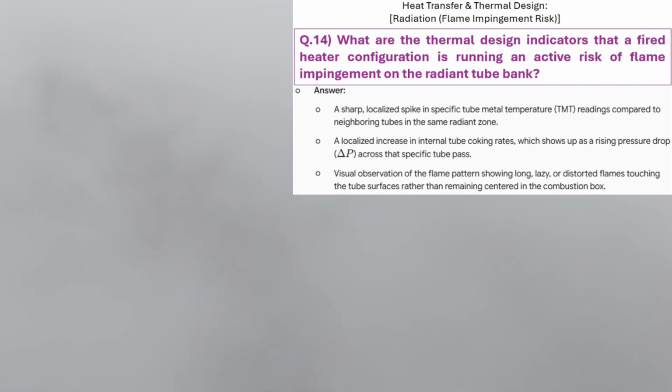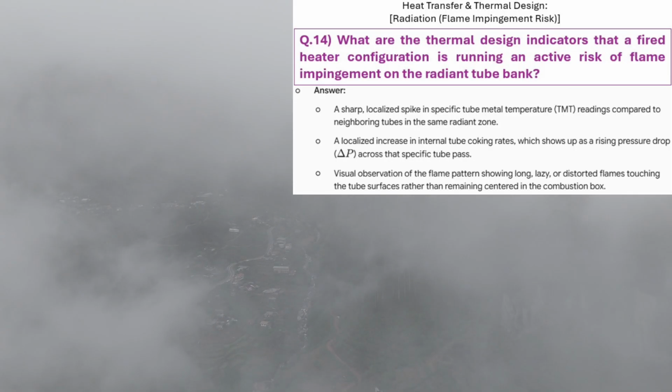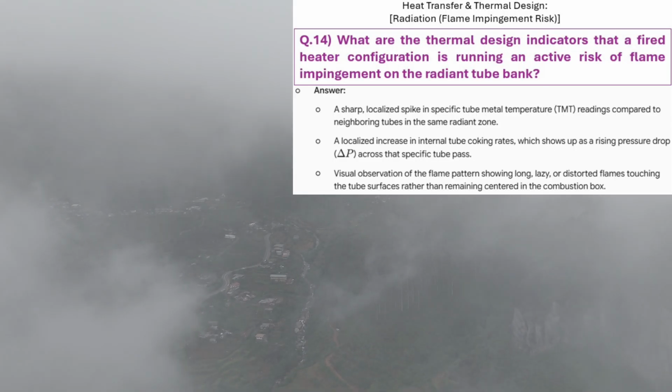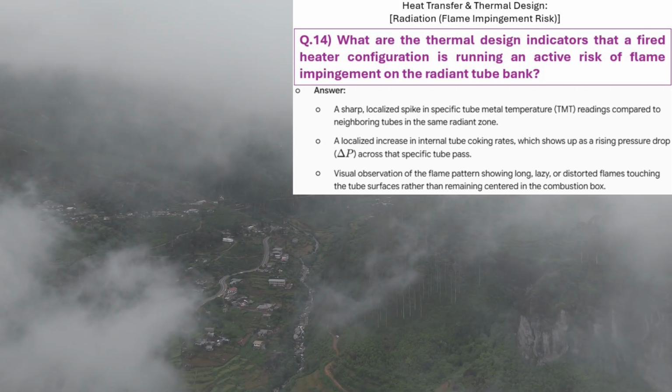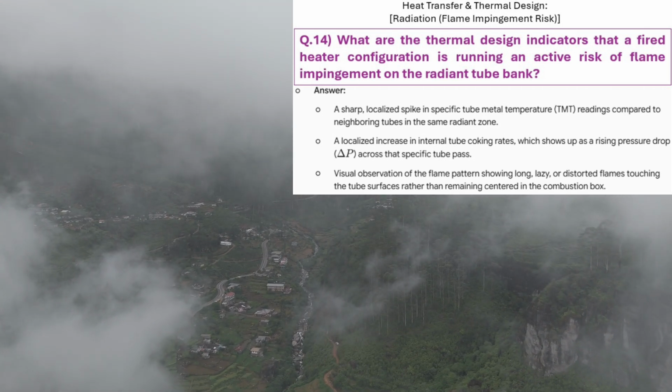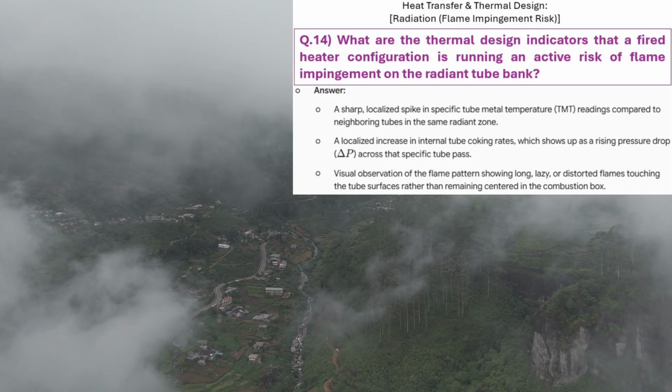Exactly. Increasing total fan velocity without adjusting individual registers can violently lift the flame off the tip, risking a total flameout. If fuel gas keeps pumping into the oxygen-rich box, it creates an immediate explosive reignition condition. So how do you actually fix the flame mechanically? You modify the specific burner physics locally: you adjust the burner tip geometry, and verify gas orificing to produce a tighter, higher velocity flame. Optimizing distribution using the primary and secondary air registers, strictly at the individual burner level to physically control flame length and prevent radial expansion.